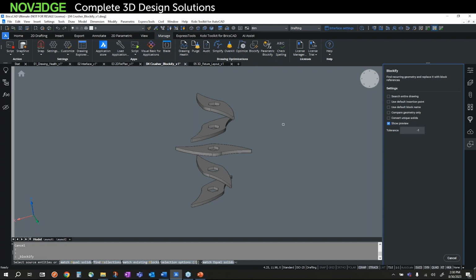Because a block definition can exist in a drawing without a block being placed, as you saw in that other drawing for the piping, there were 161 blocks in the drawing, but not physically placed, you can still use those existing blocks to define a block definition as well. But in this example, I'll use the block I just created for that blade and use it to match the existing block, as a reference to creating the new geometry.